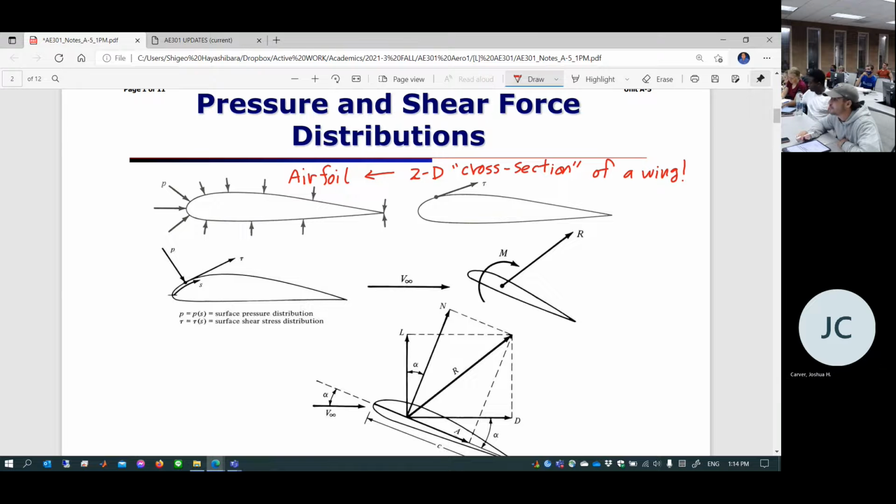That's what it is. If you took mechanics, you have two different kinds of stresses, right? One is normal stress. The other one is shear stress, of course. So those are the normal and shear forces divided by some kind of differential area, could be any area. That is going to give you two pieces of information. One is the pressure, which is distributed over the surface. The other one is shear stress, distributed over the surface.